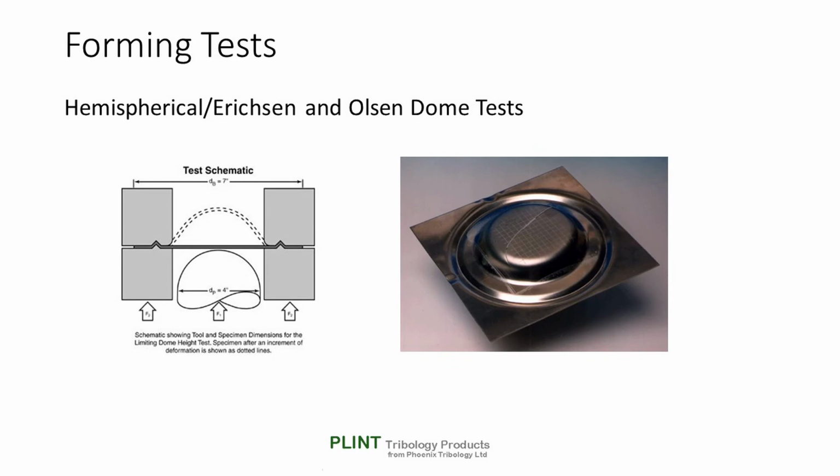Dome tests are primarily designed to assist in the evaluation of stretch formability of sheet materials. In their most basic form, the limiting dome height test involves pressing a plate sample into a dome to the point of rupture. The tests can, however, be used to investigate a range of tribological properties, including coating adhesion to the substrate in pre-coated sheet materials, influence of lubricant pre-treatment on drawing force, and the influence of tool design, surface finish and clamping force on draw-in.